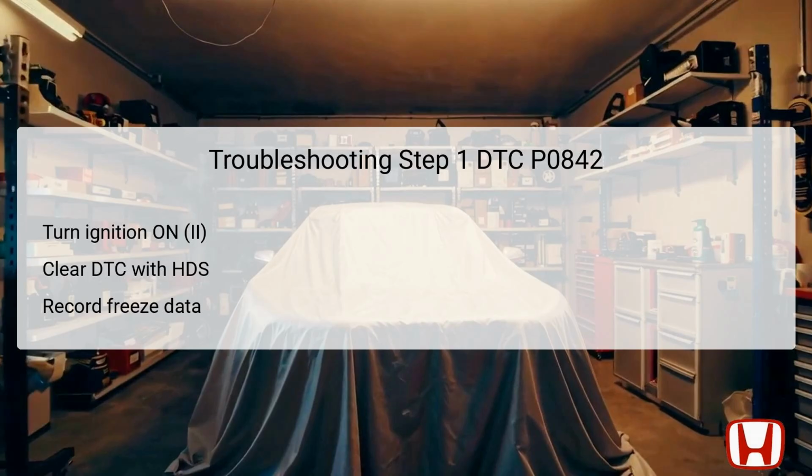The first troubleshooting step begins by turning the ignition switch to the on position, which ensures power is supplied to the vehicle's electrical systems. Following this, it's essential to clear the DTC using the Honda Diagnostic System, HDS, to reset any fault codes that may be active at the moment.